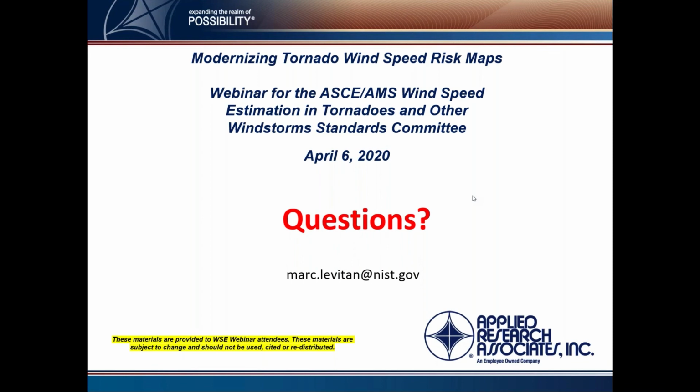They did have an effect on the climatology, and all of the tornadoes in the database have an effect. The modeling that's done to develop these wind speeds is very different from what's done for hurricanes. Of course, we have so much more actual data and so many real measurements of hurricanes. The number of hurricanes is 2 orders of magnitude less than what we have, so it's a much different modeling process that's used to develop the hurricane speed maps for the ASCE 7 standard.